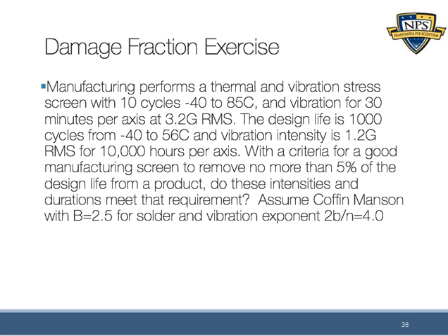So first of all, assume a Coffin-Manson model with a B value of 2.5 for solder and a vibration exponent 2B over N of a value of 4.